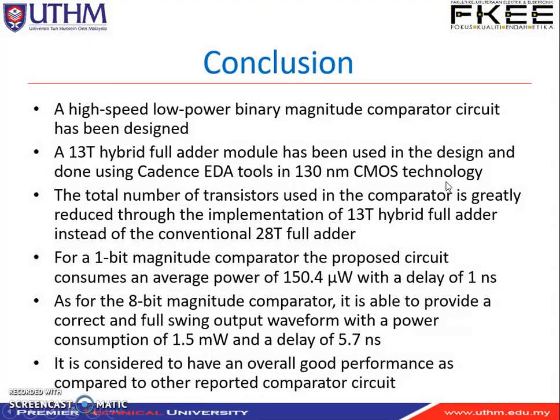As a conclusion, a high-speed, low-power binary magnitude comparator circuit has been designed. The main part is the hybrid full adder using 13 transistors, and it is done in Cadence EDA tools, 130 nanometer CMOS technology.